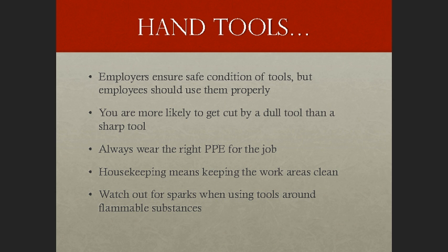Safety requires that floors be kept as clean and dry as possible to prevent accidental slips with or around dangerous hand tools. Around flammable substances, sparks produced by iron and steel hand tools can be a dangerous ignition source. Where this hazard exists, spark-resistant tools made from brass, plastic, aluminum, or wood will provide for safety.